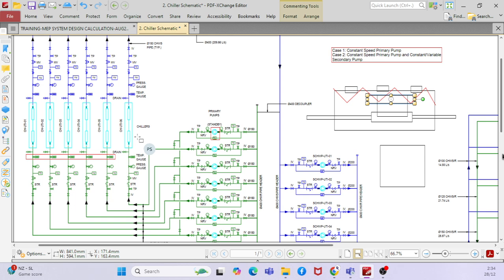The chiller will get overburdened, right? Because whatever cooling coil you have set within the chiller, that's the temperature it wants to maintain consistently. I will tell you some more. What will happen if it goes to 0 degrees Celsius? Water freezes, it becomes zero. So that will damage the coil. Yes, it will damage the coil.